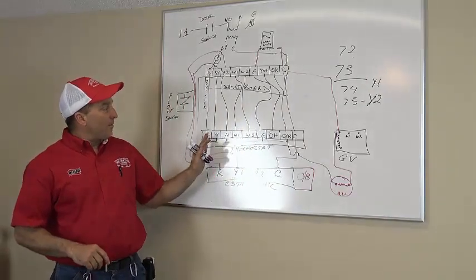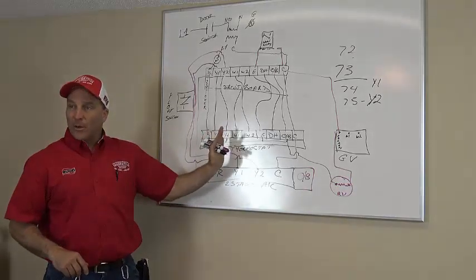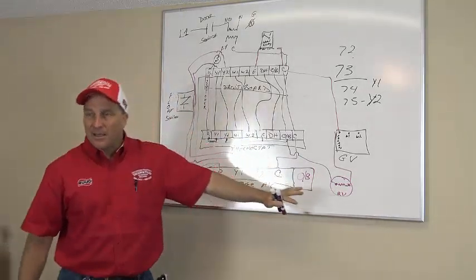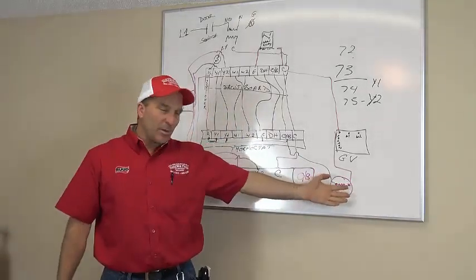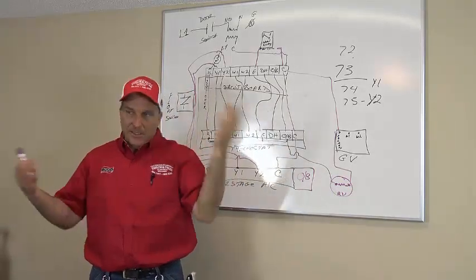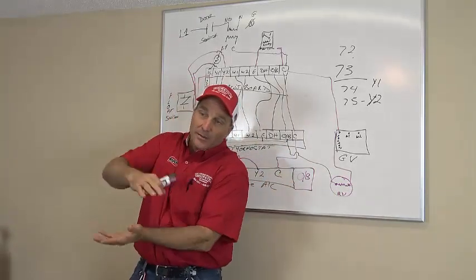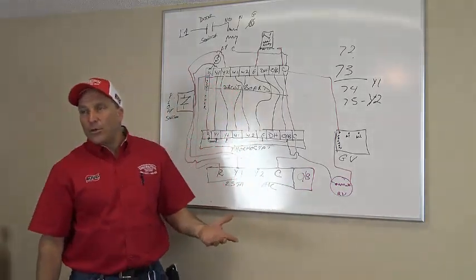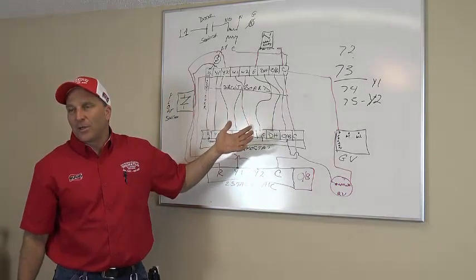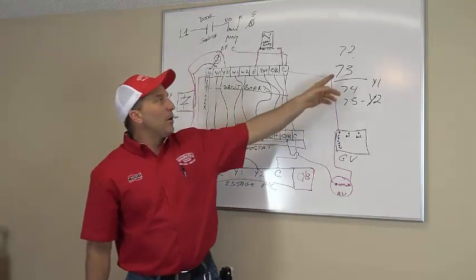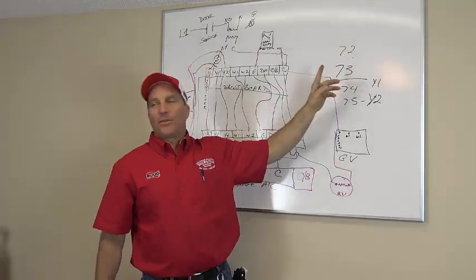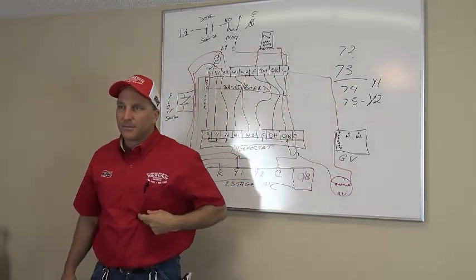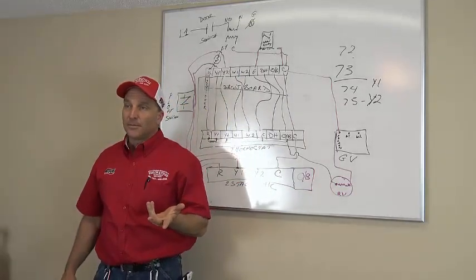Well, first stage and second stage in my cooling mode, or in my first stage heating mode in my heat pump, right? In a heat pump, what am I doing? I'm just energizing a reversing valve that reverses my refrigerant, and I still got a two-stage air conditioner running in reverse, right? That's it. Okay? Well, how does it eventually turn into gas heat? How does it eventually happen? Well, what if you go from 71, 72, 73, what if there's a 3-degree differential to kick you into the next stage? That would work, right?